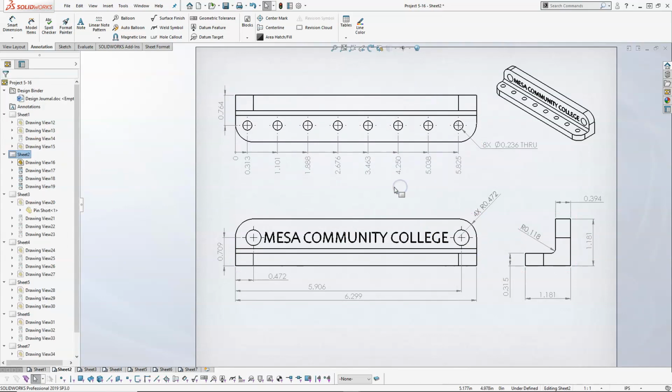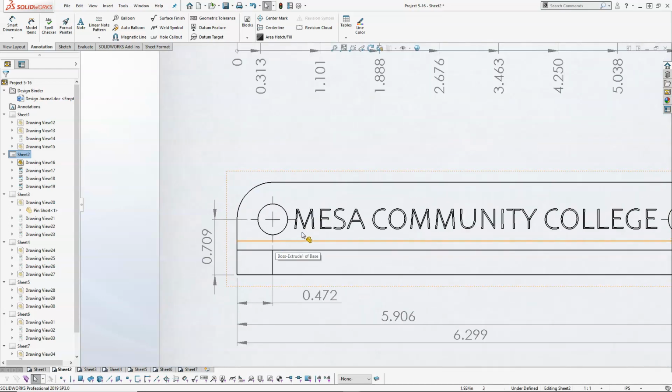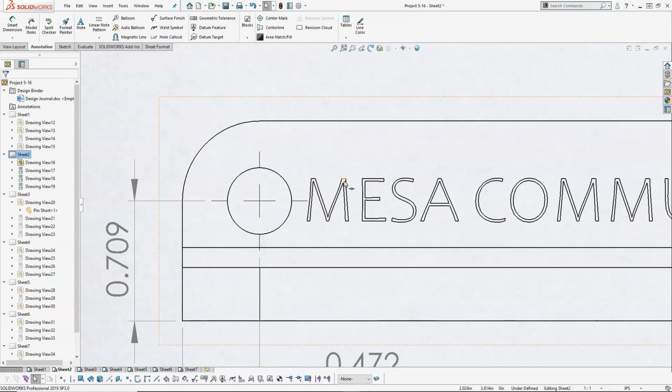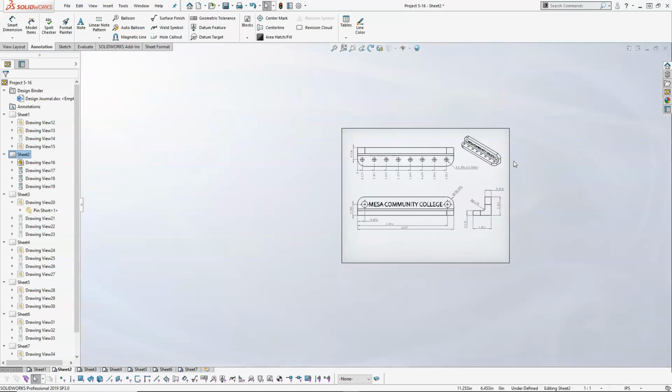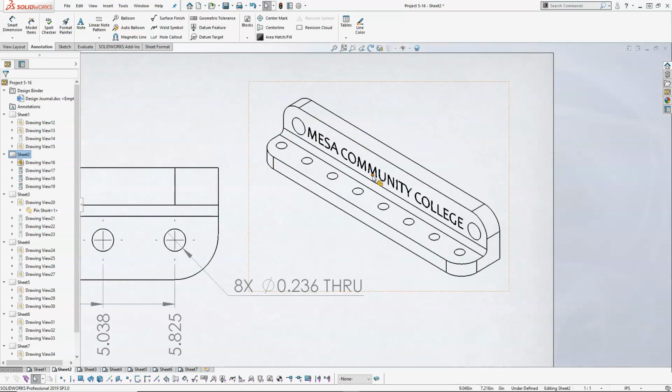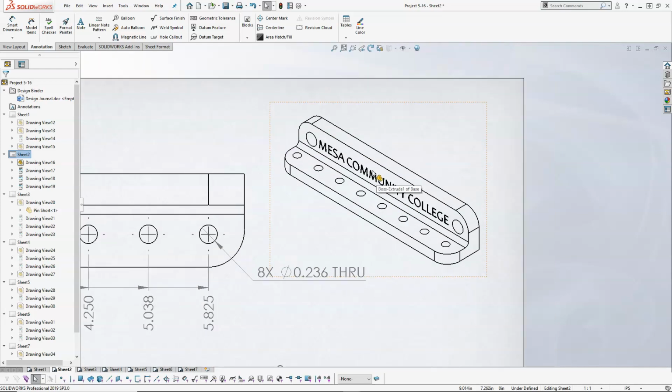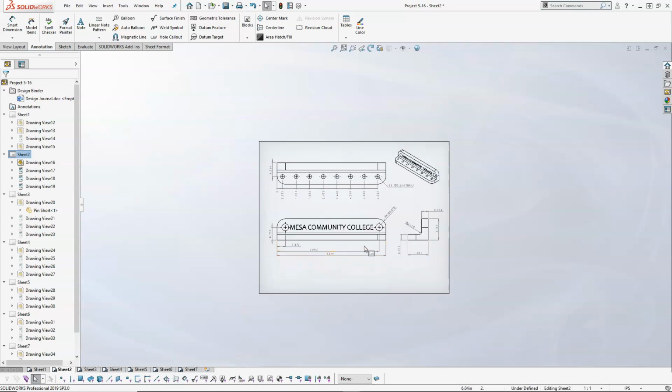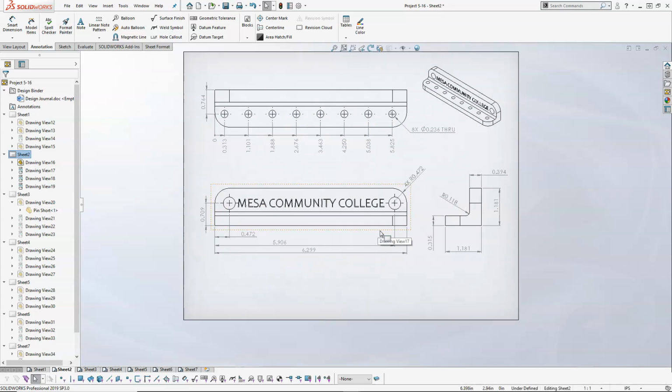And one of the things when we look at the manufacturing process, there is such a thing as a single point, which would try to trace this. And this is not any of the fonts that we create. We're probably not going to pocket these out, try to follow that exactly with a really small end mill. And because that surface is set back, it's not really going to help us. So we'll have to make some decisions when we get to the manufacturing side.